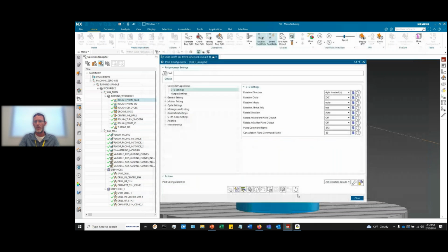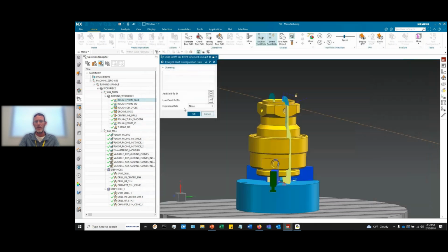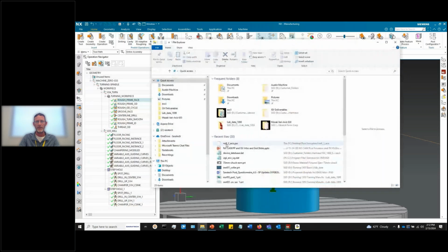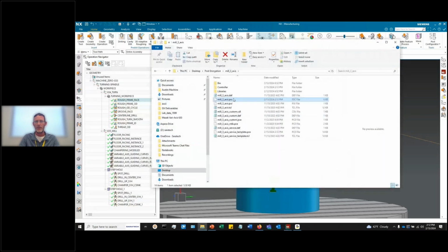And then if we wanted to do an encryption for date, then we would add an expiration date. And once I process this, then you would have a TCL file that was encrypted. So now if I come to look at that file that I just encrypted, see I have my PCE files that are encrypted TCL code. This TCL, this TCL. So the process of encrypting doesn't hinder the customer at all, period.